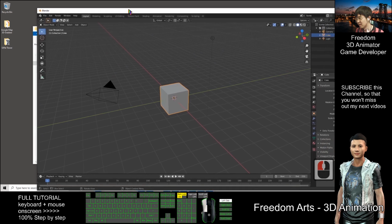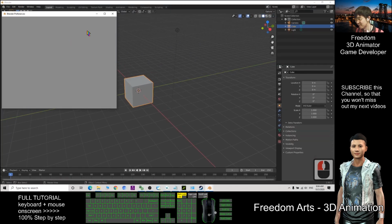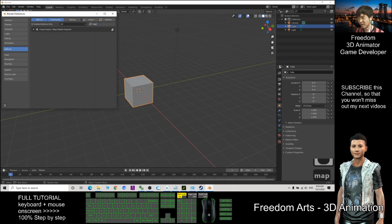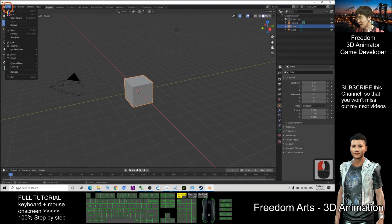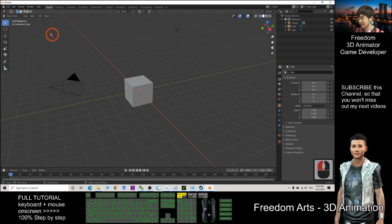Alright, so next you double check here: Edit, Preferences. You type the map here and make sure it is ticked. Make sure you tick it, and after that you close it. Then File, Import. You should be able to see an RDC Google Maps Capture here. Delete everything, including the camera, the cube, and the light. Press delete.